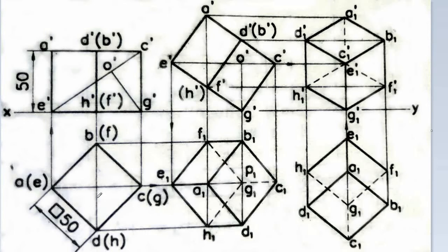And after fixing the glass cage to the base, centrally fixing the object to the glass cage, we will tilt the glass cage so that its solid diagonal is perpendicular to the vertical plane. And after that, we will get the view of the object through the walls. And that view is known as the isometric projection of that particular object.